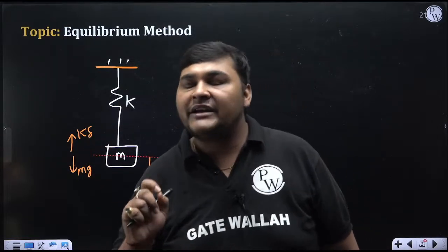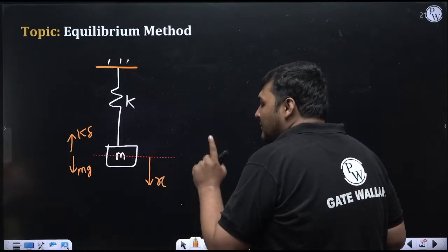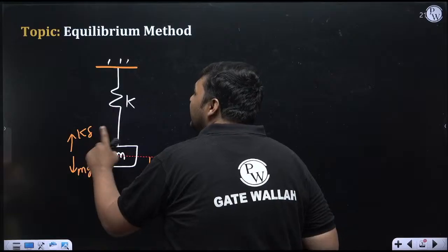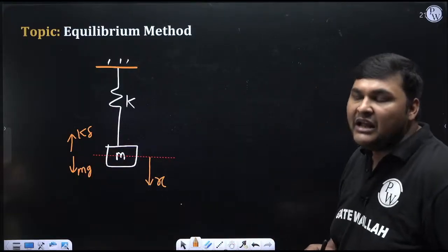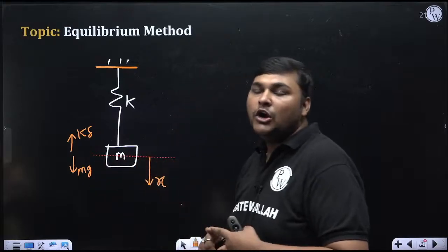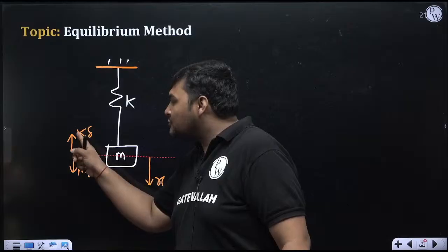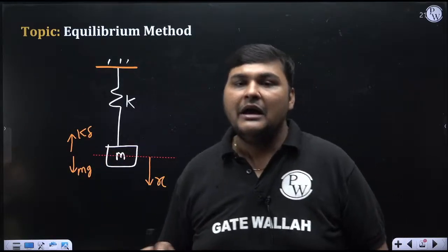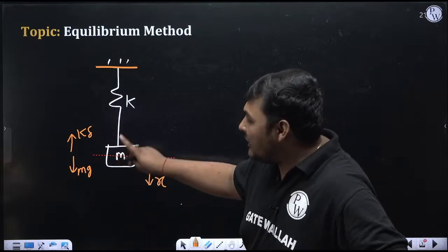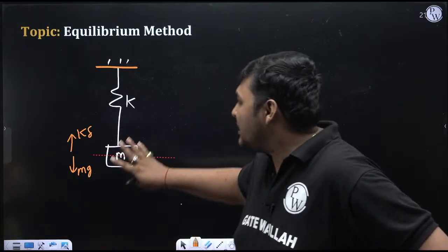So what I am trying to say is, whenever we are deriving the equation of vibration, if in the direction of vibration, due to weight, static deflection is coming in the spring, then while deriving the equation of vibration, we will neither consider the weight nor the spring force due to static deflection. Reason? Because both forces will eliminate each other. How these two forces eliminate each other, I explained right now, and we need not bother about that, because this case was a simple case.